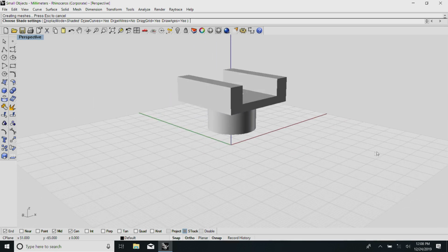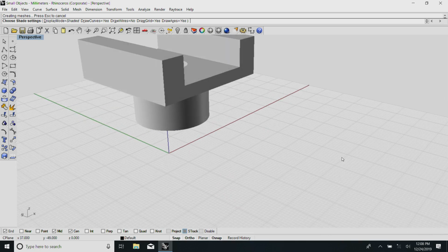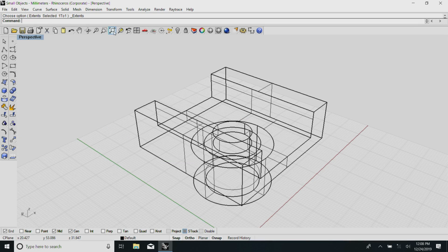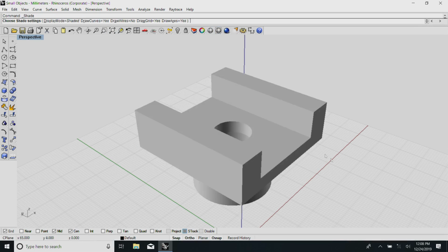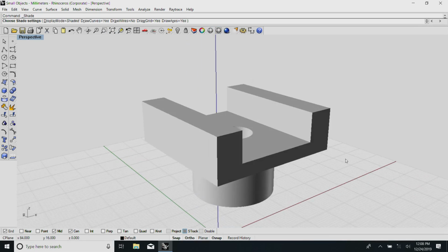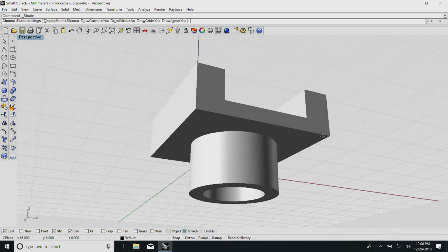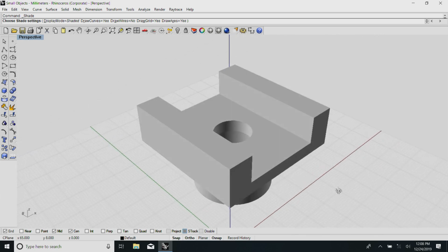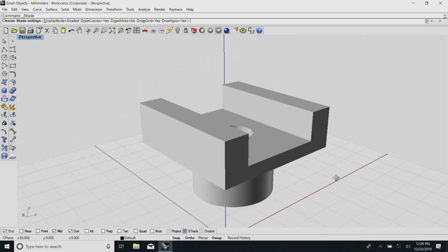One of the ways is trying to make a cross section of this, extrude it. That extrusion and those systems will come if actually in reality we are having an extrusion, and afterwards drill a hole in the extrusion. On the other side we make a pipe and fit it to that, and in one shot an equivalent thing would have been produced very easily.